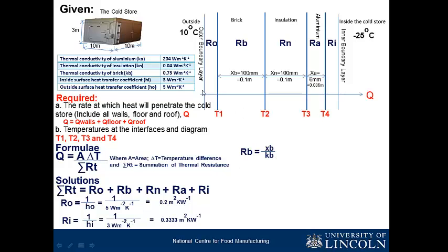So here we have a brick with a thermal conductivity of 0.75. Sorry, 0.1, which is the thickness. This is not 1, please. It's 0.1, the thickness of the brick, not 1. So 0.1, that you can see, meter. It's a thickness, it's not 1. 0.1 meter divided by 0.75, which is the thermal conductivity of the brick. Now look at the unit. If you divide 0.1 by 0.75, you have this.